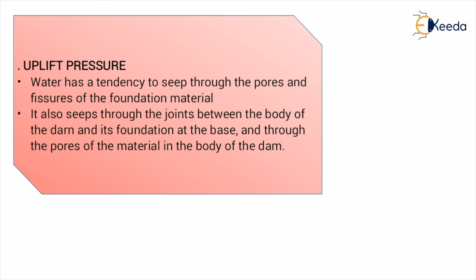Sometimes drainage galleries are also provided in the body of the dam, which release the uplift pressure built up under it. The magnitude of uplift pressure recommended at the face of the gallery is equal to the hydrostatic pressure at the toe plus one third the difference of hydrostatic pressure at the heel and toe. So we have the formula when we want to find the uplift pressure at the heel, as you have seen in the diagram of a gravity dam.